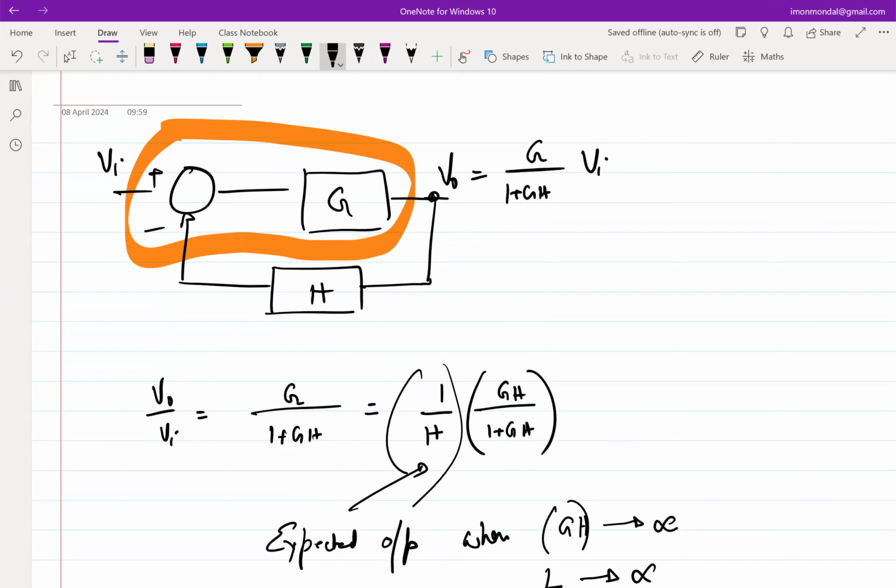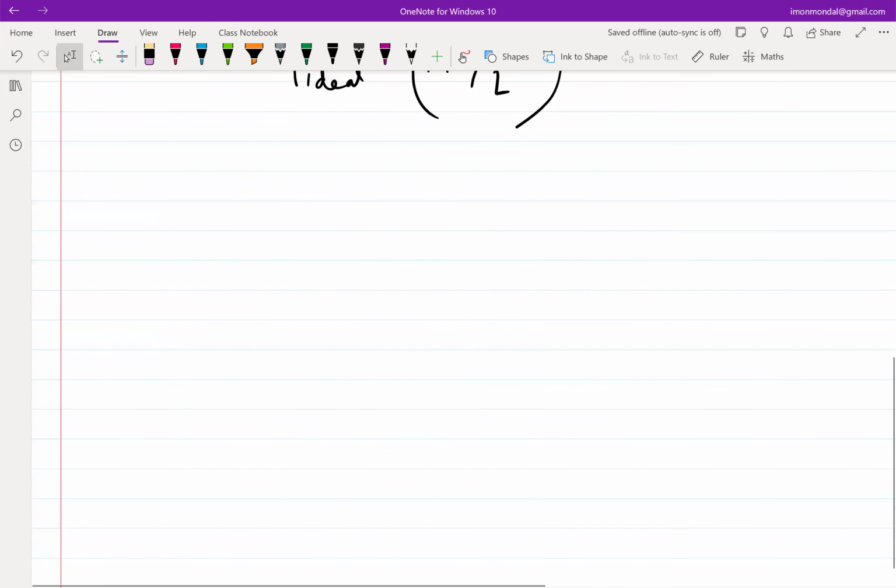And we also know how to make an amplifier which senses the difference of two signals, right? Even a common source amplifier senses the difference of two signals, but it has an issue that it loads the input in one of its terminals. If you send something to the source terminal, it is going to load whatever it is driving. So then we came up with another topology, which was a differential amplifier. And then we said that we'll replace this plus minus gain times G term with that topology. And that topology was this.